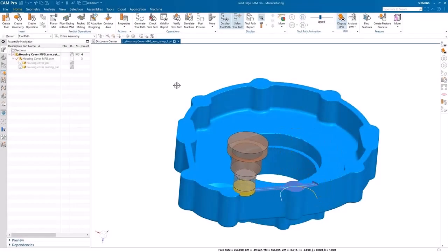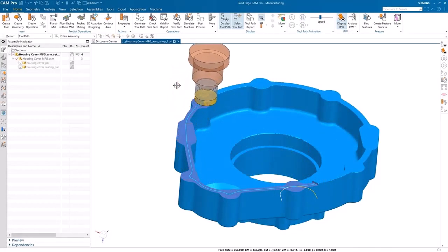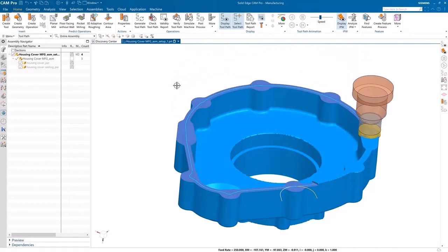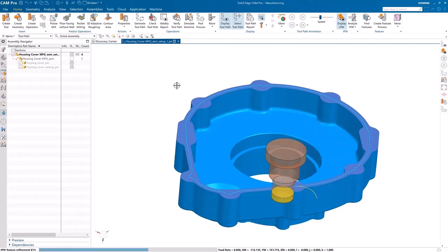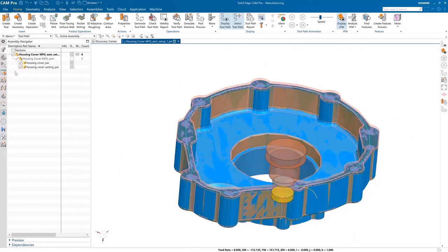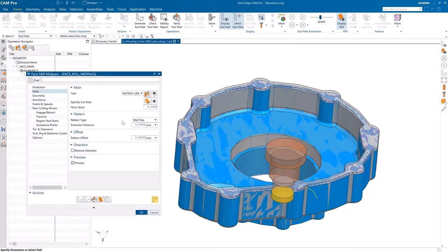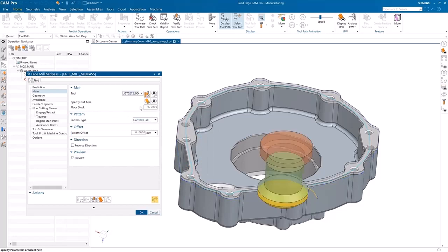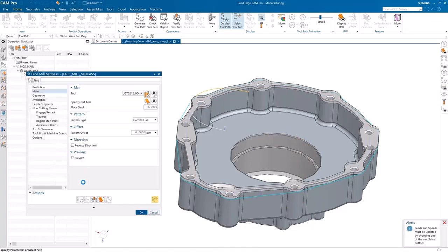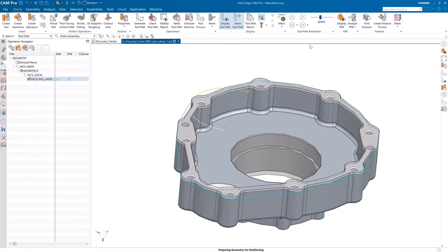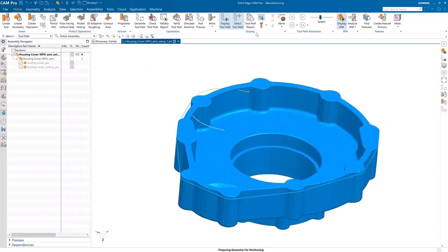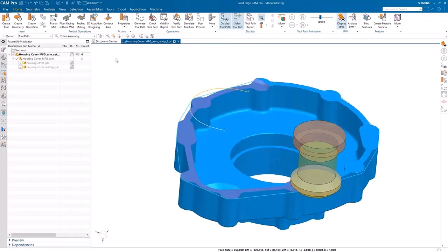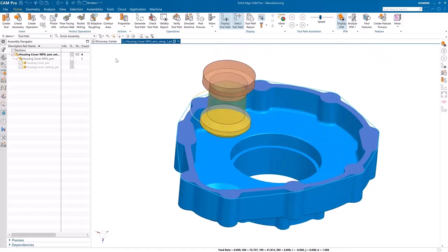Generate toolpaths on flat surfaces with complex shapes using the face mill mid-pass operation. This feature, perfect for the milling of cast flanges or any other oddly shaped flat surface, automatically calculates the midline distance between the edges of a face and places a toolpath on it. For users that desire the cutter to be off-center of the flange, the operation can also create a toolpath along a shape described as the convex hull of the face. The face mill mid-pass operation can greatly improve productivity for this type of machining, eliminating the need to manually create a boundary line for the cutter to follow. This allows you to create the operation in minutes as opposed to hours.